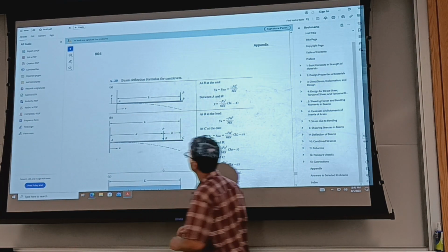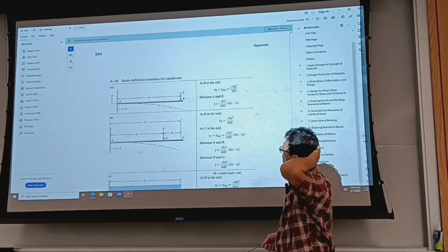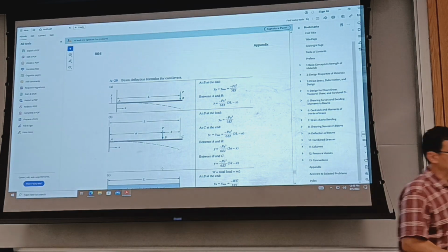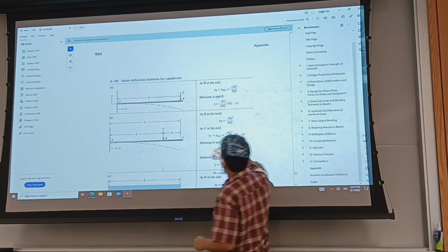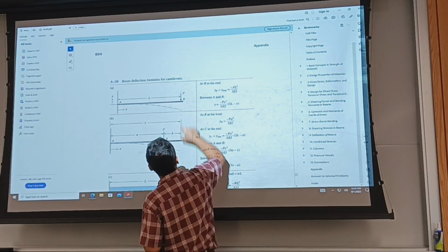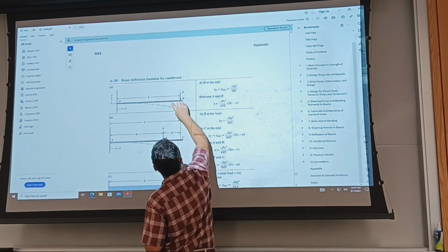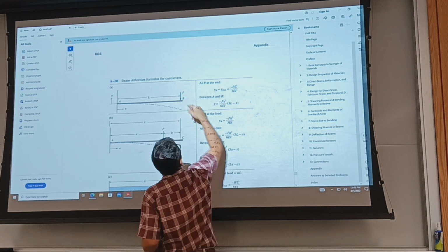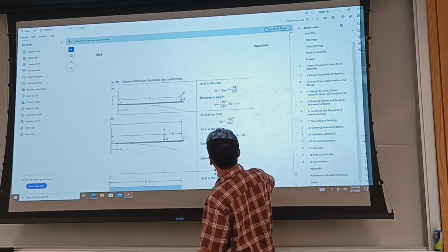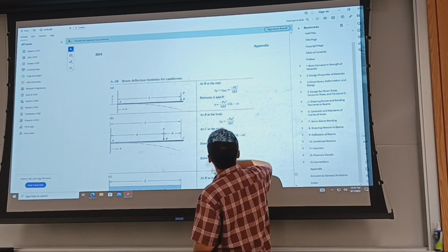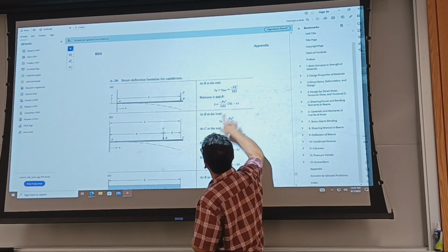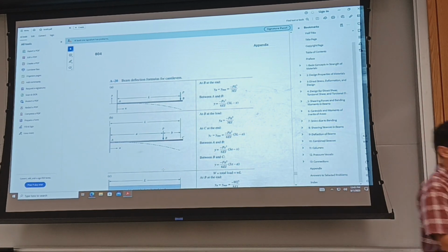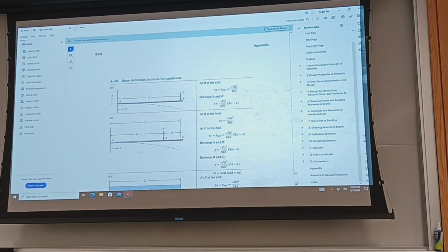You don't mix notation. There will be two separate cases. So I make this negative and then calculate the deflection for the individual cases. One will be down, one will be up. Same amount, but with a plus. And then I set this equal to this, and it gets me what? It gets me this force due to the support of the cantilever, if it makes sense.